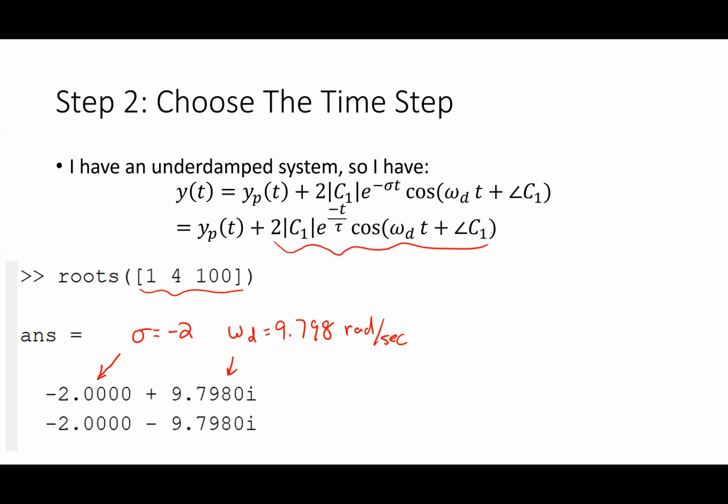Okay. Now I've got to ask myself some more questions about this. What did I do here? Basically, I converted this so it had an e to the -t over tau look to it. I did that because if I have an exponential, what's the important time feature? This ends in 5 tau. So I needed to make sure that I captured that entire transient piece.